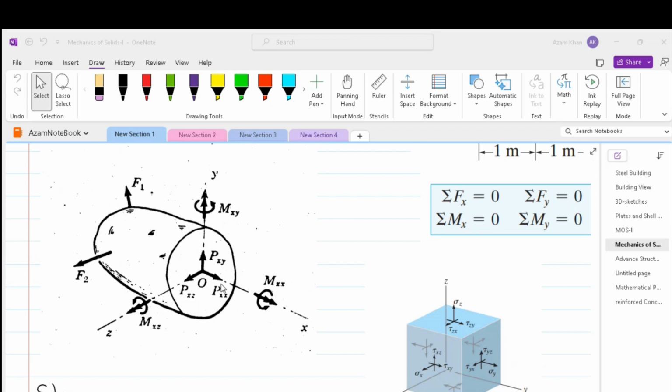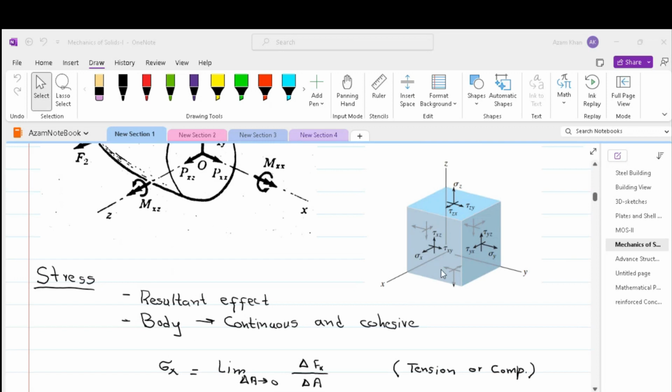So to cut a long story short, we end up with a cube which has got six faces, and every face is made up of three different types of stresses. One of the stresses is axial and the other two are shear. The axial stress is directed outwardly from the surface. However, the shear stresses are lying within the surface.